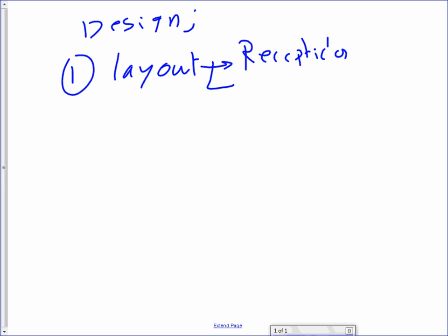And you need to also lay out lighting outlets. We need to find where we need receptacles in the house and where we need the lighting outlets. That's step number one when you design these things. Now we're done with this.